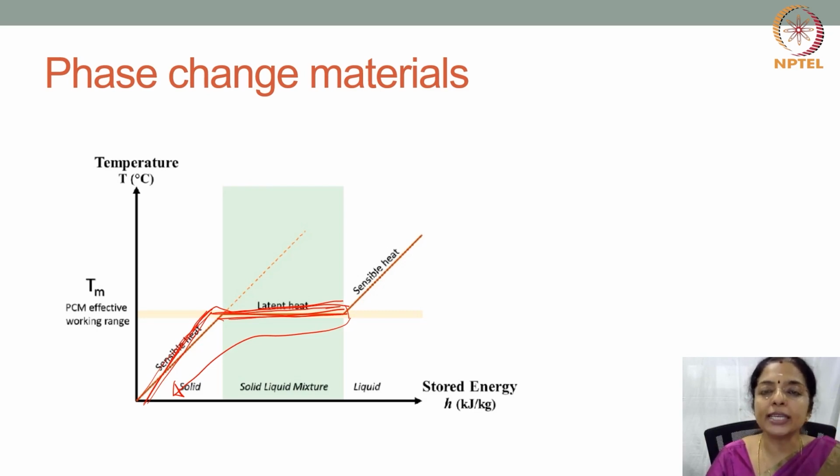So phase change material incorporated glazing units refer to innovative building material that combine phase change materials with glazing systems in order to enhance the energy efficiency of buildings. These units aim to address the challenges of regulating indoor temperature by leveraging the latent heat absorption and release properties of the phase change materials.